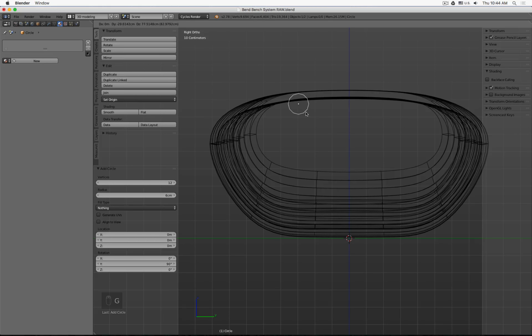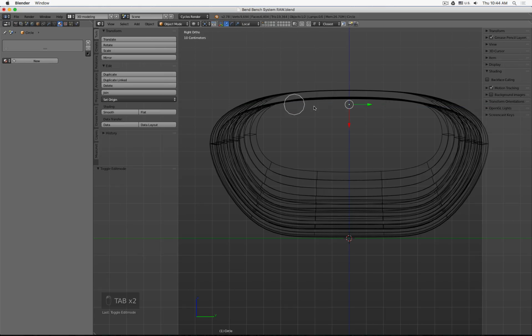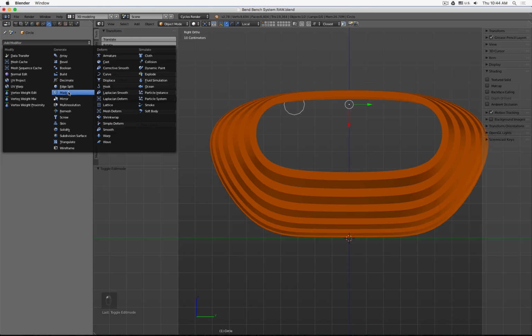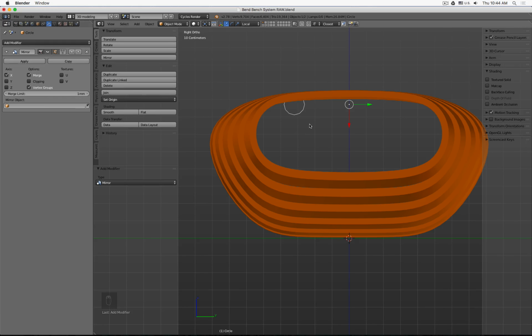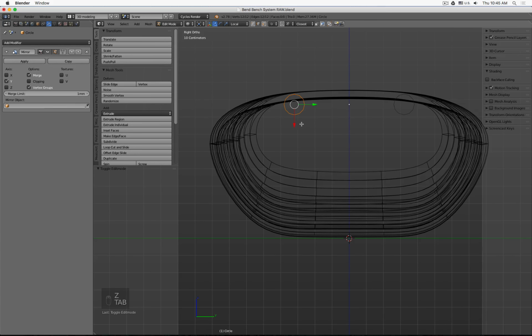Okay, and then we don't move it to the position, but we can move the object up, and then in edit mode I move this over. Why did I do this? Well, because if I add a mirror modifier, which by default works over the object's object center point. There you see now this way I mirror it over its own center point, and I don't have to use an array modifier. Perfect. I can move this a little bit down maybe, or there.